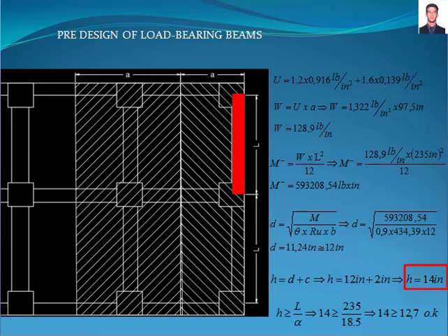Now, using table 9.3.1.1 of the American Concrete Institute 318 standard, we verify that the height of the beam is inside the maximum height allowed by the standard. This beam has one end continuous and the applicable condition is 18.5. We make the verification and the height of the beam is inside the parameters.